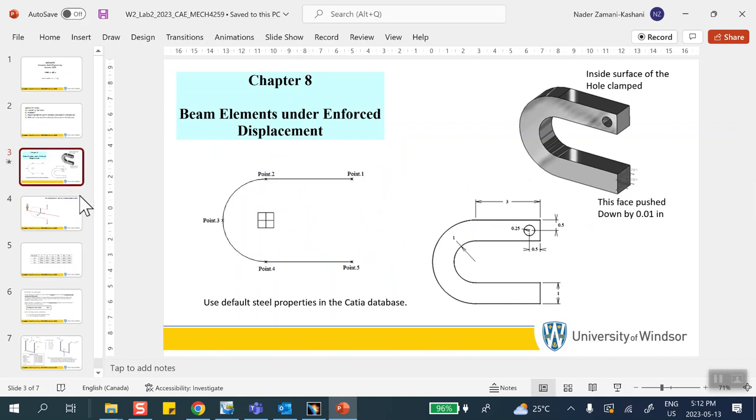Okay, one other thing that you should realize, if you're going to do this with a beam element, this line should not start here and go all the way to the top. It should go by the median curve here. So 1 inch plus half an inch. So this line for modeling with beam is going to be 1 inch plus half an inch, half of this height. Okay, good. So let's go ahead and start this.